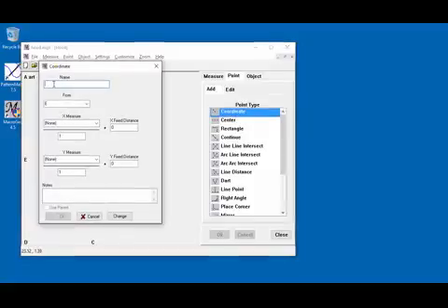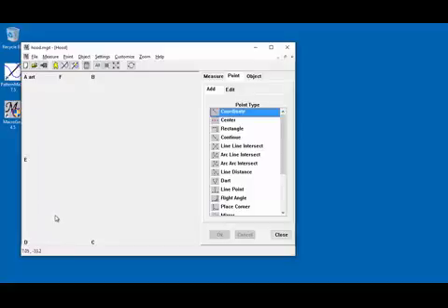We're going to call it point F. And what it actually is the curve at the back where the hood begins. It will always be the same distance from B, so we're going to use a fixed distance value. I'm going to enter that value here. It's going to be -8. That means 8 to the left. And we're referencing from point B. Click OK. Excellent.